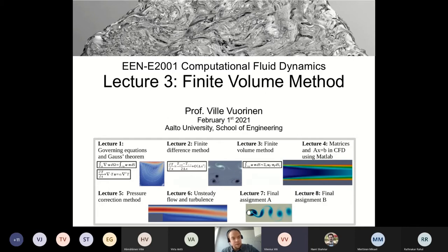I was wondering, expanding on that, about a combination of solid mechanics and fluid mechanics, like the interaction of the two, how would that go? Yeah, that's a problem type called fluid structure interaction. For example, you could have some vibrating surface in a fluid, like a vibrating propeller. There you would have two ways to go. One approach can be done in OpenFOAM, but some people have also coupled two codes, so that you take, let's say, a finite element code to solve for the solid vibrations, and OpenFOAM to solve for the fluid motion.